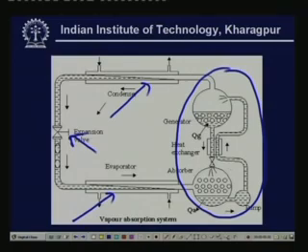Here, instead of a mechanical compressor, we have a component called absorber, a component called generator, and a solution pump. Let me explain the working principle here. Again, let us begin right after the expansion valve. After the expansion valve, we have low temperature, low pressure liquid, and this liquid enters the evaporator, where it takes heat from the surrounding water in this case and produces a refrigeration effect in the surroundings. And during this process, the liquid becomes a vapor.